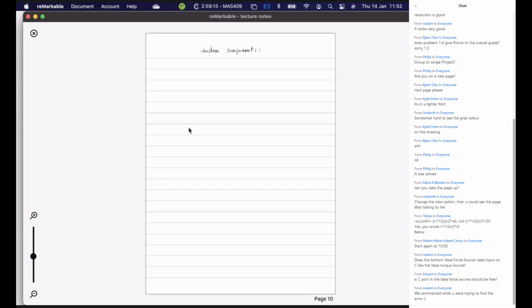I created already some custom components like a pulley, and I will give you a file for this. What you need is to load them in Simscape when you open your model. You do this in MATLAB: when you have the prompt, you write ssc underscore build.